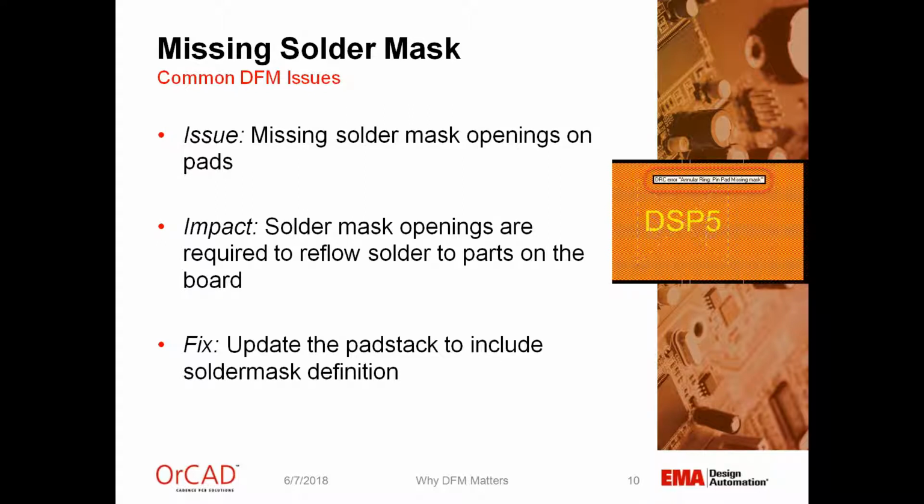Next one is missing solder mask. So missing solder mask openings on pads. These are required so that you can reflow or solder parts on the board. So if there's no opening in the mask, we're not going to be able to bond the part if the pad is covered over with solder mask. Chances are the manufacturer is going to find this, but if they weren't able to find it or they missed something, that could cause a problem. So we have a way to detect that now. And the simple fix is we just update the pad stack to include that solder mask definition.